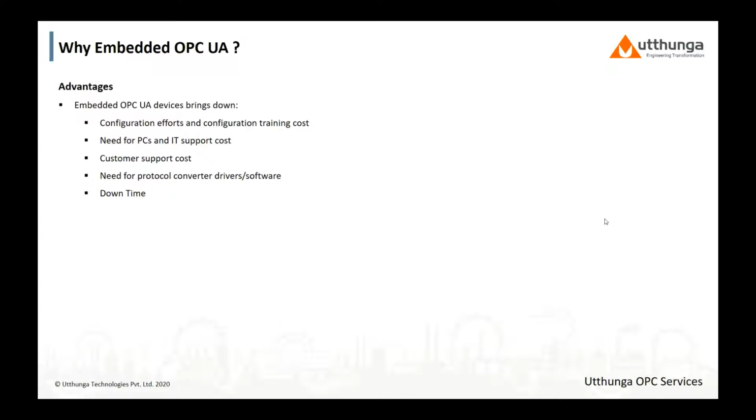Otherwise, the PC software where OPC is installed would have an EtherNet/IP driver to talk to an EtherNet/IP device, get the data, consolidate it, and expose it via an OPC UA server. Now the device itself will have OPC UA, which eliminates the need for protocol converters and drivers. And because of the ease of plug and play, overall downtime will be much less.